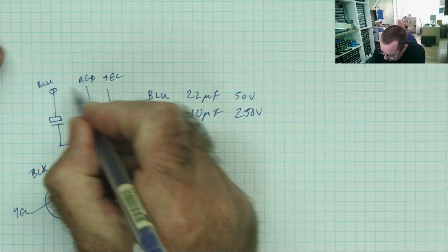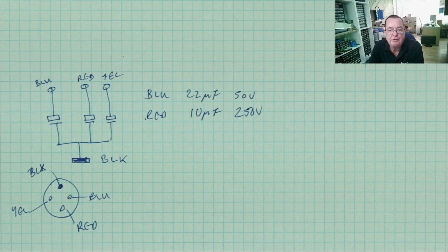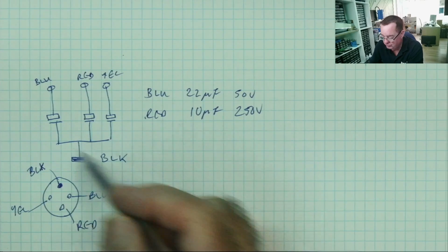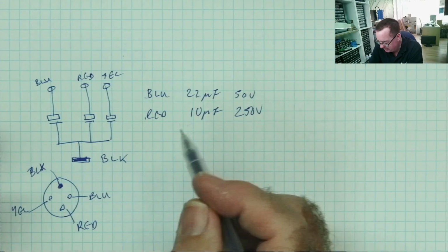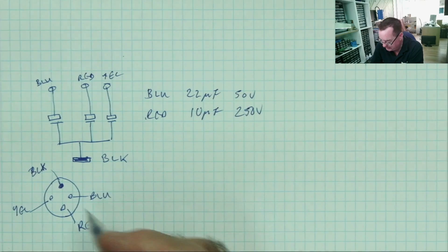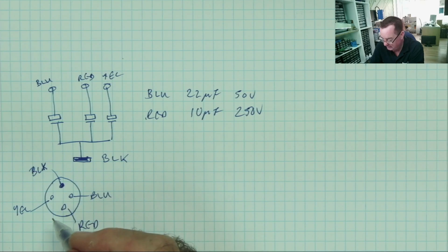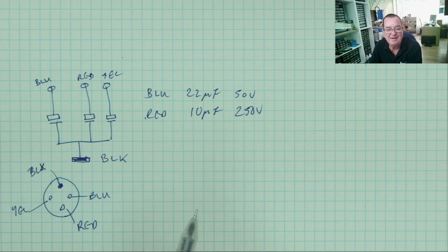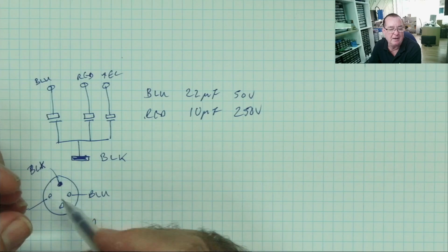Now, these vintage capacitors are long since gone. If you're trying to repair this sort of equipment, just a hint actually, you could obviously replace this with 3 individual capacitors, but if you're trying to keep the kit looking as much as you can like it was originally, if you prise this top off the capacitor, the metal can, and you take all the crap, that's the faulty capacitors, out, you'll end up with a hollow can in the top.